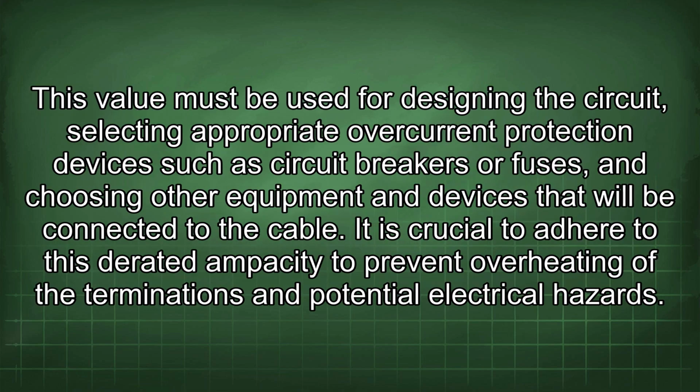This value must be used for designing the circuit, selecting appropriate overcurrent protection devices such as circuit breakers or fuses, and choosing other equipment and devices that will be connected to the cable. It is crucial to adhere to this derated ampacity to prevent overheating of the terminations and potential electrical hazards.